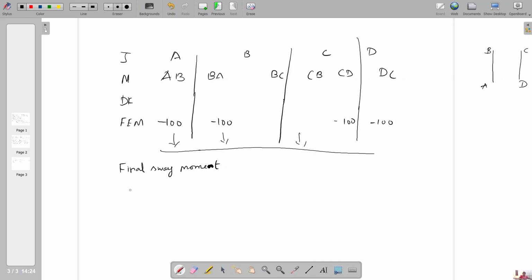And the same procedure should be repeated. You consider the column and you draw the respective moment direction, and also you draw the horizontal reaction direction. First of all, you assume the direction of horizontal reaction. According to the results you obtain, you can change the direction. You take moment about B equal to 0 and calculate HA dash.